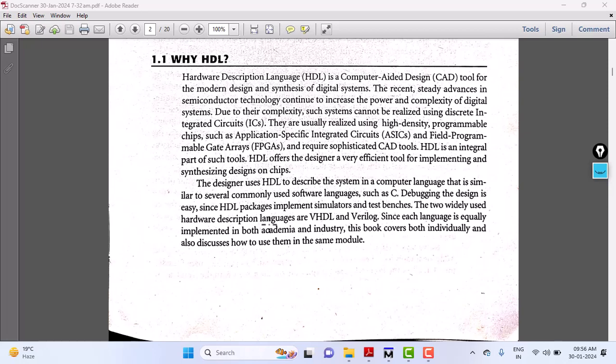It's very difficult, right? Now, what industry expects is you have to develop a design. You also should develop what is called a test bench. You understand the meaning of test bench? Test bench is another Verilog code which will test the designs. Our actual design is an AND gate, and for the AND gate, you should write a test bench. What is a test bench now? Test bench is another Verilog code which will test the AND gate.